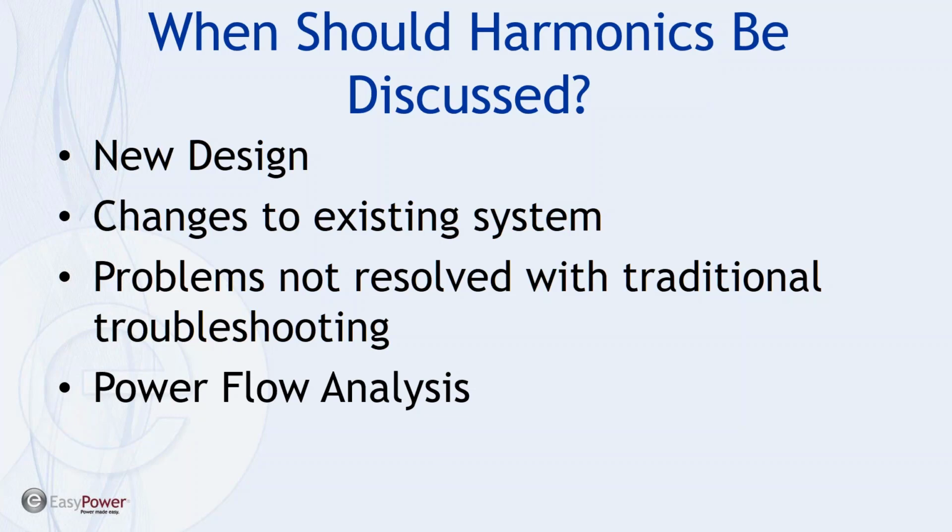Now, all this comes to bear if we start having problems in a system, and having a power flow analysis available puts us one step ahead when it comes to talking about harmonics. Better still, if you have a power flow model that reflects the normal operations of the plant, including harmonic content, let's call it the harmonic signature of the system, then the task of troubleshooting becomes simpler when things change.